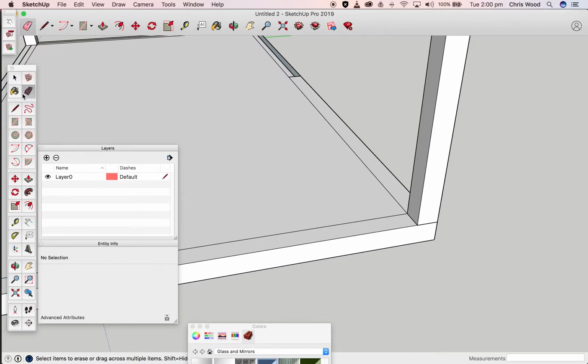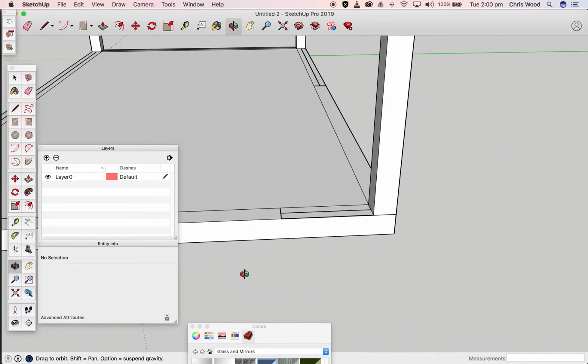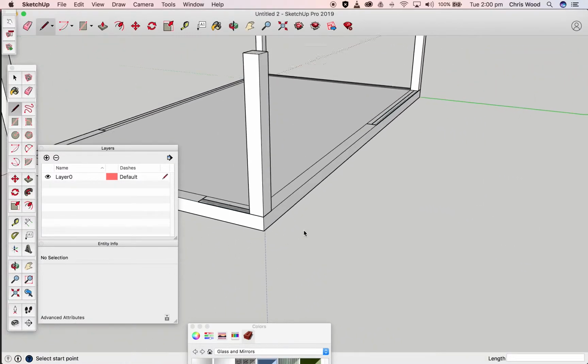If we're doing doors, it's the same sort of thing. So let's make this door fairly wide. Let's make it 1200 wide, which gives us an extra wide door, and that gives us room to get a wheelchair through there, so the house is nice and accessible. I'm just going to lock that off, and do the same thing. I'm going to draw through where the line sits, so we can see the midpoint of where the door will sit here as well. Okay, so that's all pretty good.